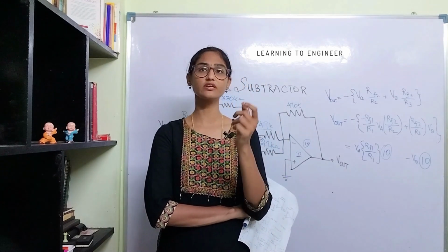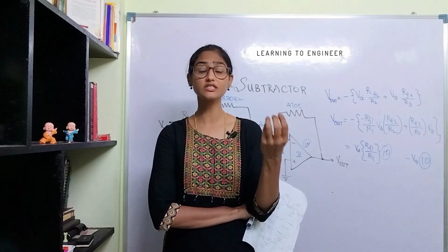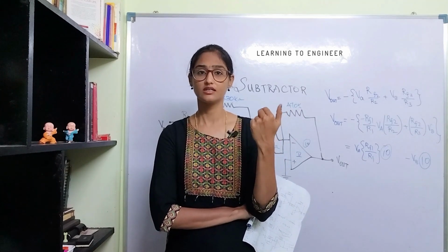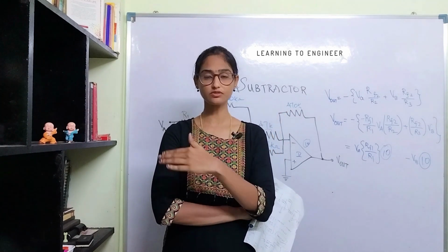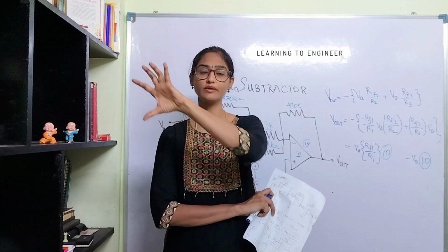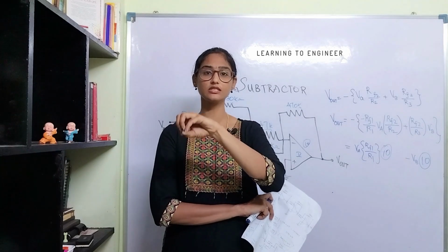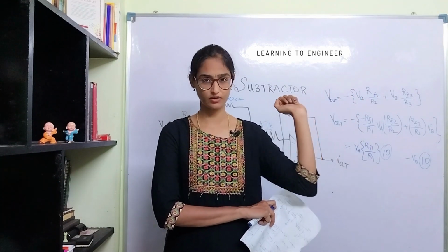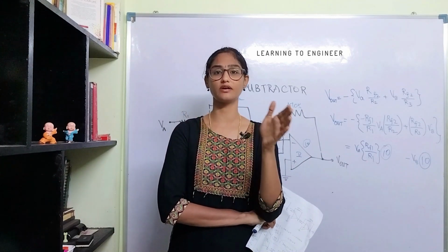Okay, let us say for example, you are getting a temperature output of, let us say, 100 degrees Celsius. It will be in a voltage of, let us say, 1 or 2 microvolts, and this 1 or 2 microvolts has to be amplified by this system in order to be sent to a readout where you can see the reading. Okay, so for that kind of amplification we use gain multipliers.